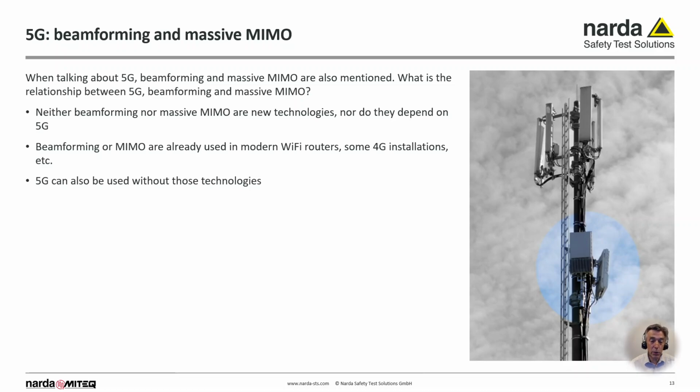There we will not use massive MIMO antennas because at those frequencies, a massive MIMO antenna will have a surface of several square meters. So you don't want to have an antenna with 5, 6, 7 square meters surface on your rooftop. No way. Okay. So at the moment, the only massive MIMO antennas I know, they are operating in the frequency range around 3.5 gigahertz and higher.